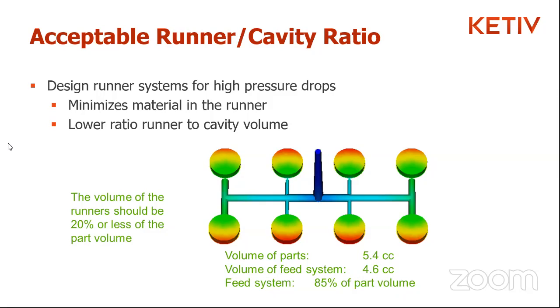For sure. But there's a lot of complex issues that go into optimizing feed systems. It boils down to, what are your goals? What's your quality criteria for the component? The material itself, how sensitive that may be to shear imbalances, or material residence time, degradation. There's no easy button. And we'll touch a little bit more on that in the next session, but one of the messages is just as much thought should be put into the feed systems and the cooling systems for our molds when we get to that point.